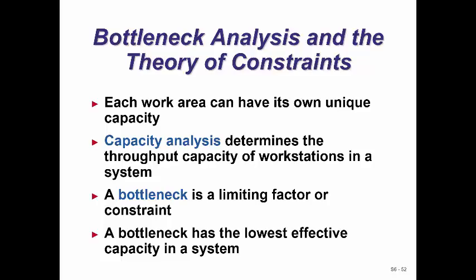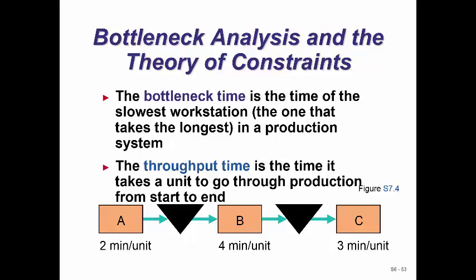If you've got one machine with slow output, the place where things are always backing up, I think we understand what a bottleneck is; it's kind of common sense. The thing with a bottleneck, though, is if you make any improvements anywhere else in the process other than the bottleneck, you're kind of fooling yourself, because the bottleneck is always going to be the one item in the production line that takes the longest.